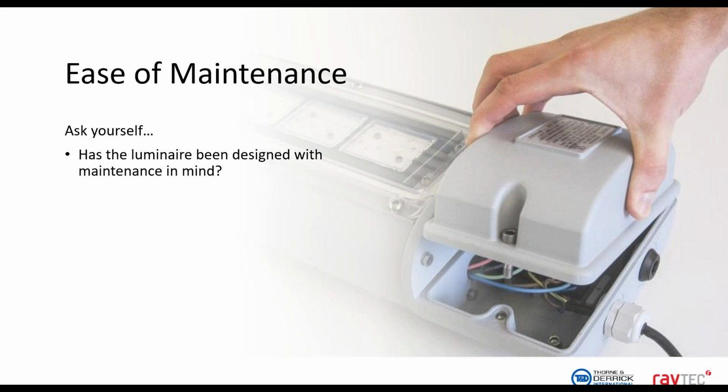But that's not necessarily the case with all linear products. Some may be what we call sealed for life, where they're sealed or encapsulated as part of the manufacturing process, and opening one of these fittings could invalidate its hazardous area certification.